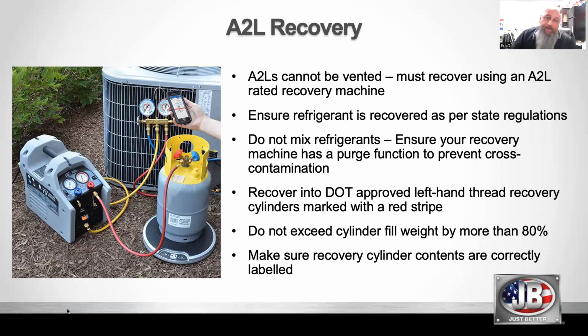Yeah, primarily, the new equipment will have the little flammability stickers or labeling on them, indicating that they do contain a substance that is classified as flammable, even though it's just barely flammable. And then there will also be a new UL listed label that is going to be required to be filled out by installing and servicing technicians. Right, and there's something about having to record the charge every time, the total charge of the system? Yep, that's that UL listed label I'm referring to. You actually have to record your evacuation level, your nitrogen pressure level, all that has to be recorded, and it's not deemed optional. These are all new requirements. Mandatory. Yes, absolutely.